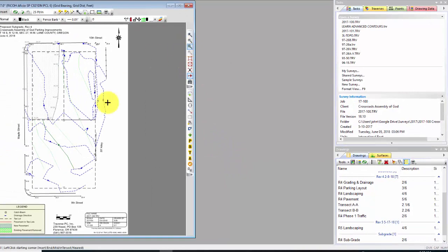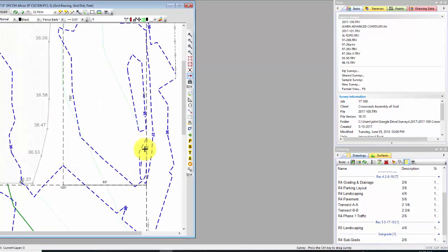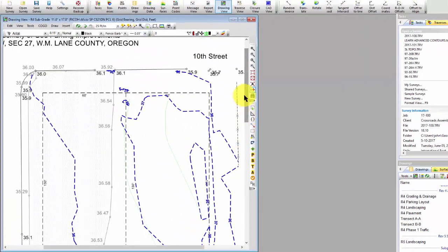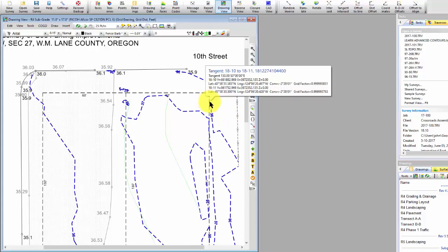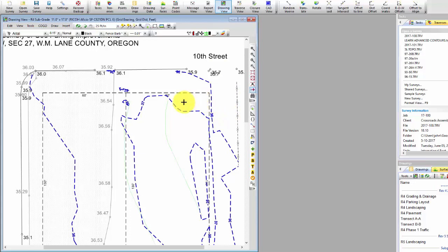And I said, okay, I've got certain things I need to work with here. I've got elevations at the edge of the pavement and at the sidewalk over here that I need to carry across. This is my 2% left to right. I'm going to end up with some elevation over here, but I've got an alley here. And beyond the pavement, I've got 5 feet to the property line. So I've got to have my grade up to the pavement.